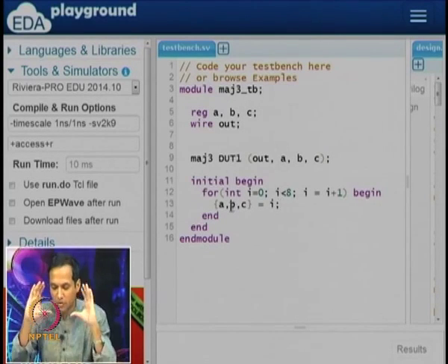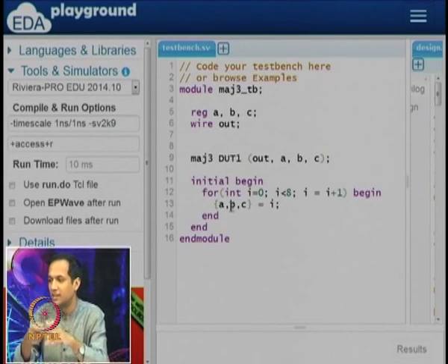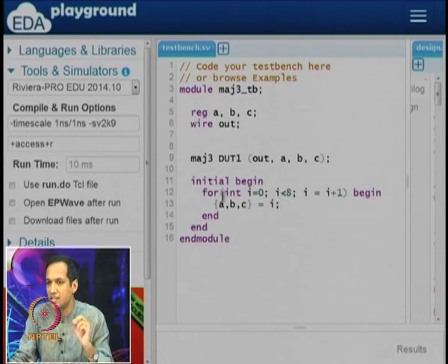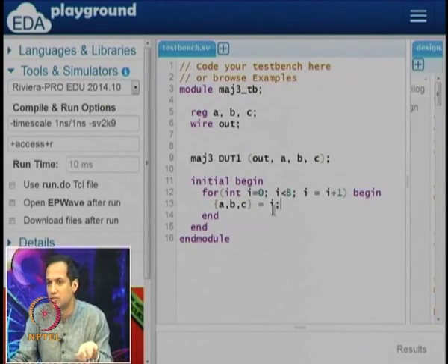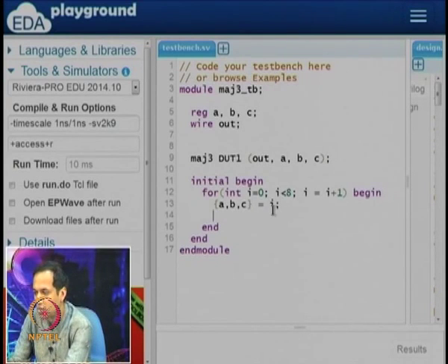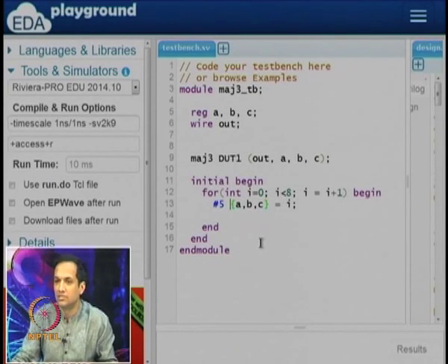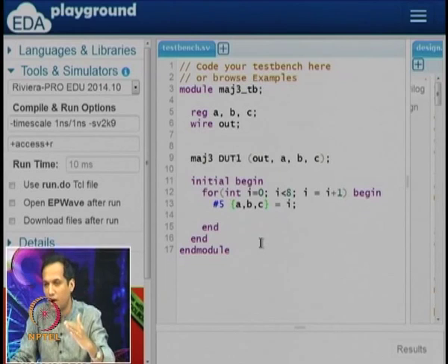So with this we are able to now see that A, B, C can actually take the inputs. Remember, if you go back to the circuit, you need to be able to connect the pins A, B and C to power supply, right. We have done something now. What we have done is we are now able to take different values of A, B and C because I is changing. I will start with 0, 0, 0, then it will go to 0, 0, 1 and then 0, 1, 0 and so on, right. And I also want to do this every 5 time units or so. So every 5 time units I will give one input, after 5 time units I am going to give another input and so on.